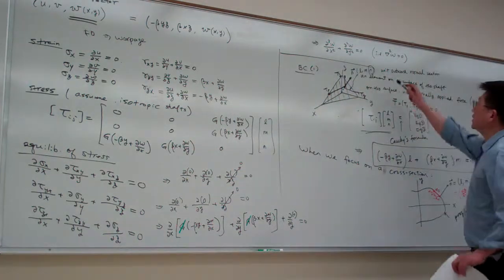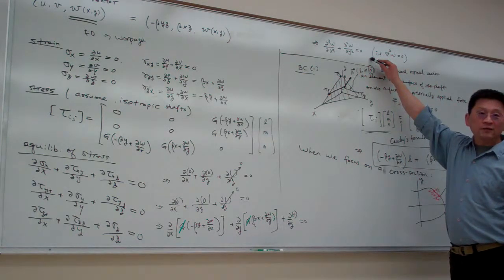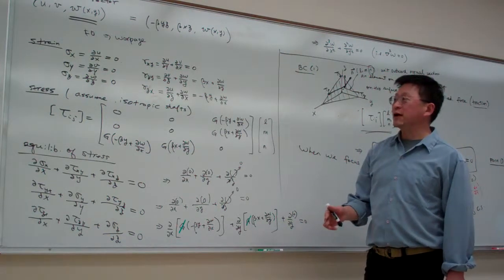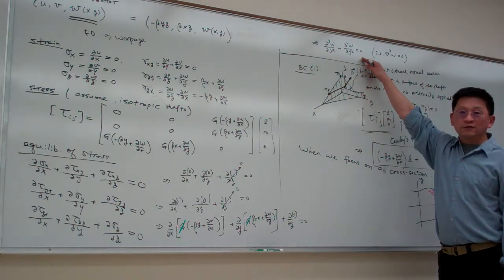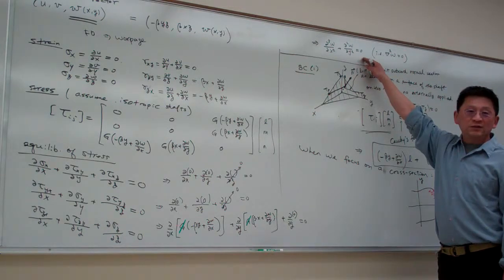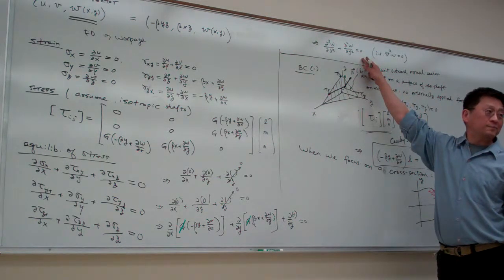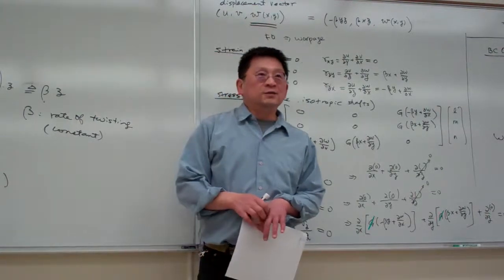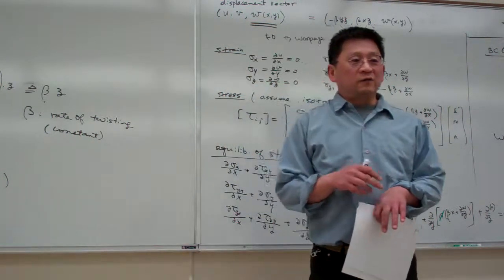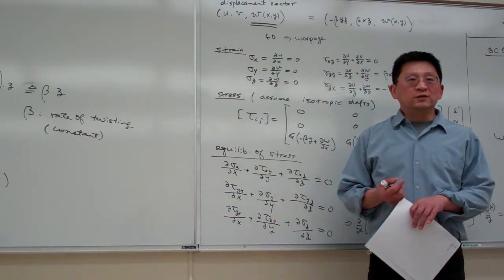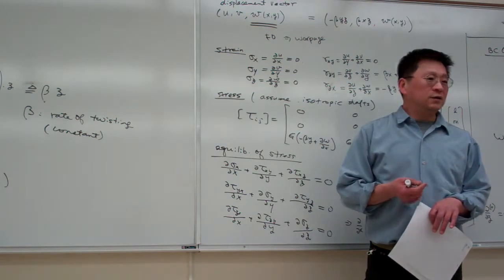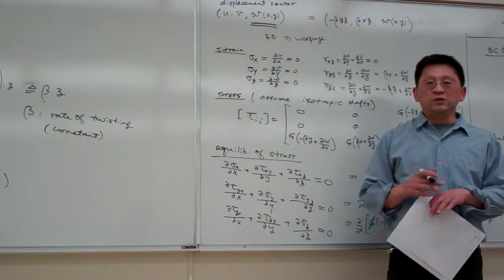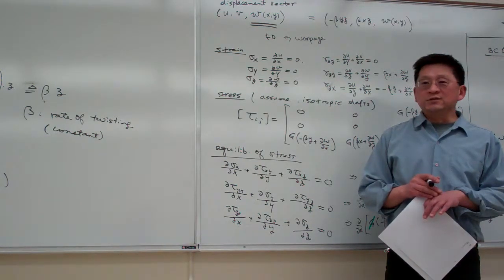W will be solved by this one. Okay. So eventually, I can tell you the torsion of the prismatic shaft is going to come down to the solution of the Laplace equation here. And we don't need to go in that direction. For simple geometry, we have another quick way, and that's the reason we have two solution strategies. One is called the invariant solution method, the handout I gave you. And we have another approach I'm going to introduce. And at that point, we pretty much finish the whole lectures for this semester.